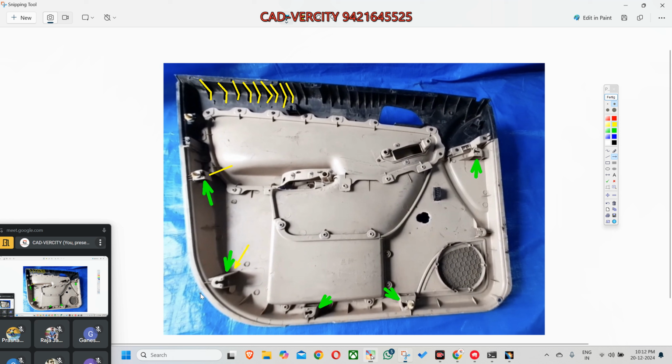Okay. Raja, do you have any doubt regarding this part? No, sir. Sir, how do you decide the lifter or slider? Okay, yes. Who can tell me? Who can tell Ganesh how he will decide whether it is a lifter or slider? For external undercuts, we use sliders. For internal undercuts, we use lifters. Awesome.